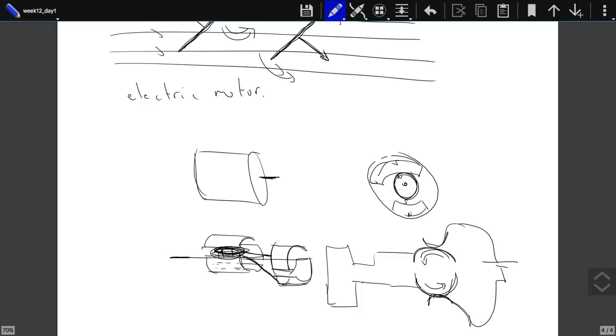So as that thing is rotating, after every half a turn, the direction of the current changes. So that is one way how you can obtain this flipping motion. Or if you want, you can just change it, depending on your design of the motor. Instead of 2, you can put 4 of them. So at every turn, it flips direction twice, not once.